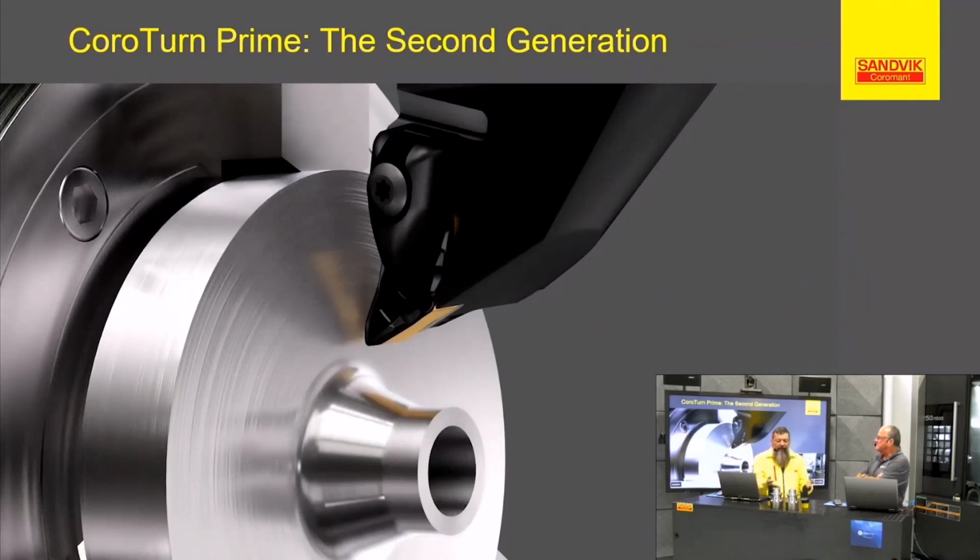That's simply taking advantage of physics, Andy. That's all we're doing. Okay, we take advantage of those physics to be able to feed harder. The chip is thinner, so we can spin faster. All these things add up to this 30, 40, 50% sometimes cycle reduction. And the interesting thing is we also get better tool life, right? Or we can if we're properly dialed in.